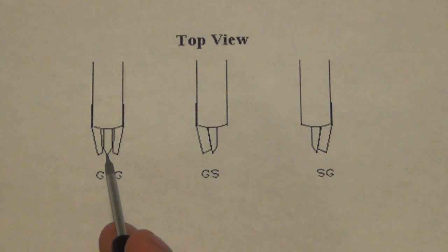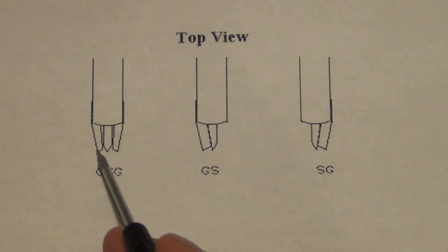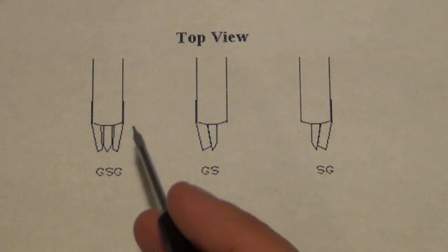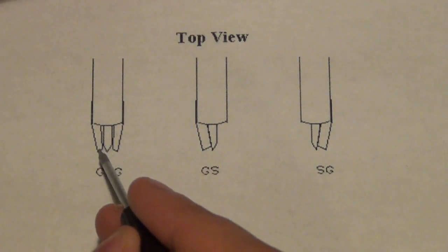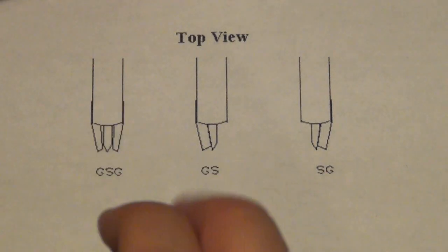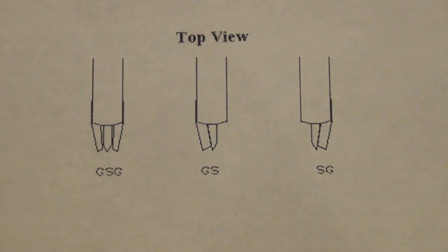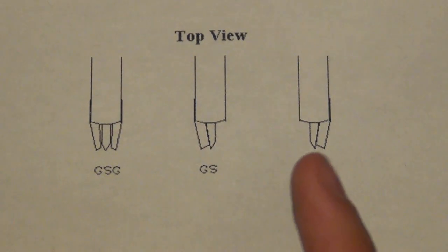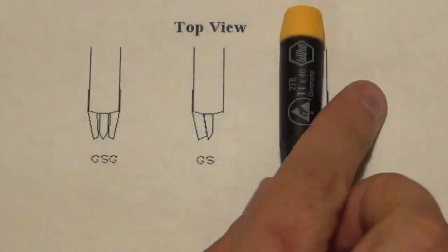We were talking about integrated circuits, and you bring these and you land them directly on top of your circuit. So on your integrated circuit side, you place pads that are designed to accept this interface, and then you put this on a stable table and so on, and you bring it and then you land it directly on your integrated circuit, and that allows you to take signals in and out of your circuit.